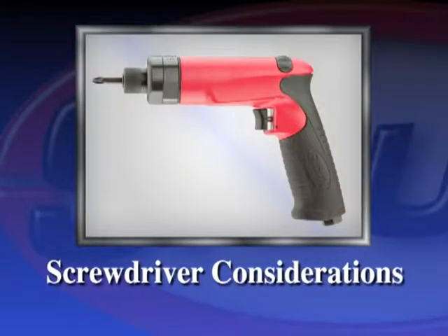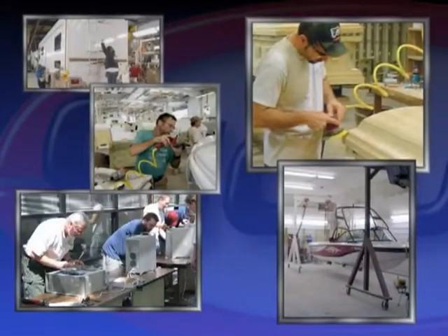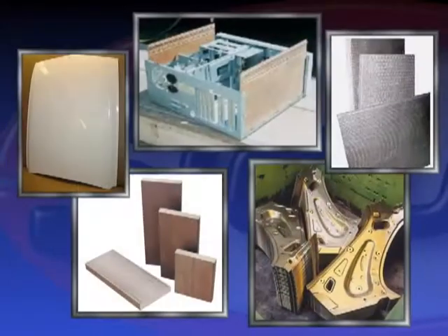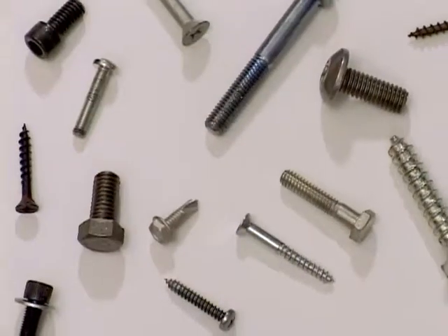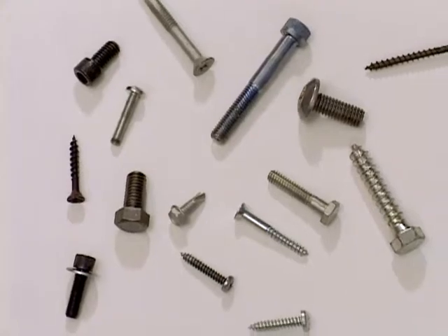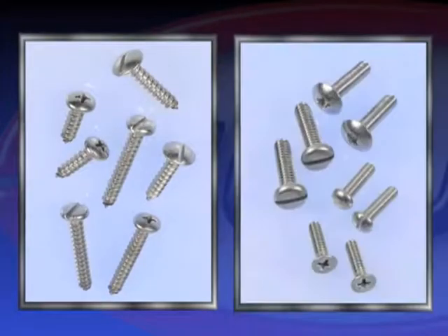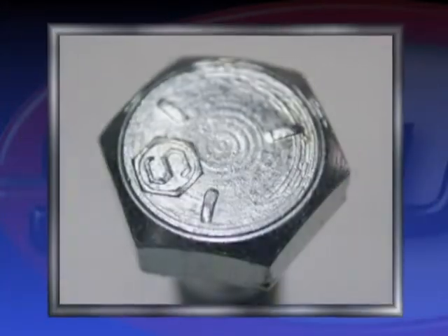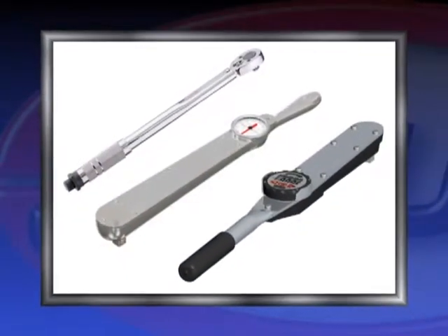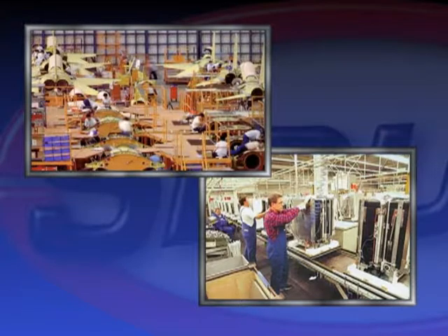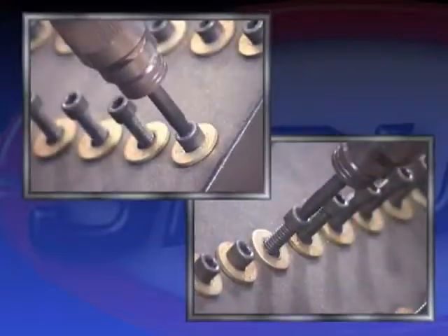Consideration needs to be given to what is being assembled, what material is involved, what type of screw or nut is being driven, what type of head, what screw size, standard or metric, what bolt grade class, what torque and how is it measured, what torque accuracy is required, is it run-down or seated torque,